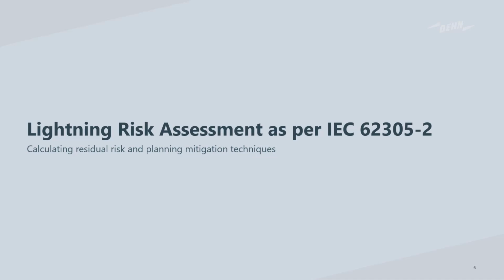Now moving on to the lightning risk assessment portion. As I mentioned, it's according to the IEC standard in this case. So the IEC standard that we talk about for risk assessment is IEC 62305-2. This standard is actually written for buildings, as there's no lightning risk analysis standard written for PV plants as of yet. The lightning protection standards for PV, however, do recommend that you use this method and adopt it in a way that you could use it on a PV plant. So this just forms part of experience and best practices to be able to apply this to a PV plant, but there's no formal standard for PV plants, and it could be very subjective.